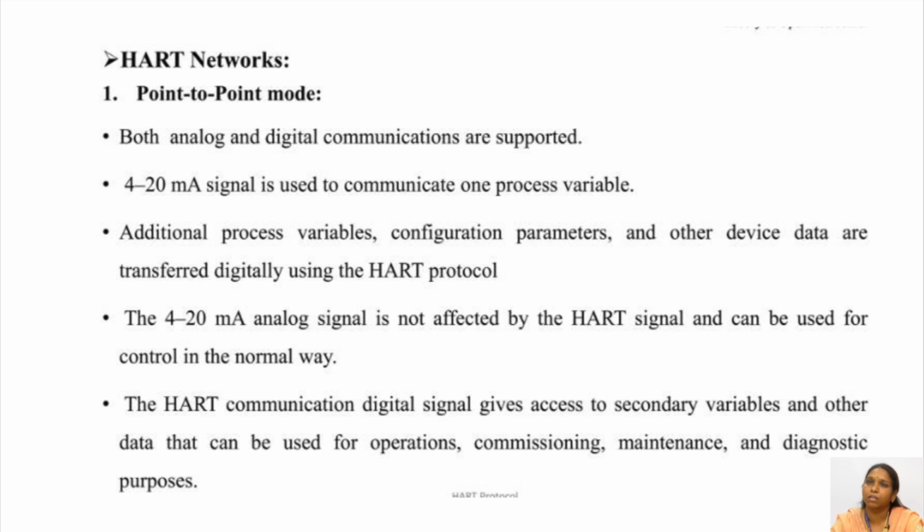HART network. First one, the point to point mode. Both analog and digital communications are supported. A 4 to 20 milliampere signal is used to communicate one process variable. Additional process variables, configuration parameters and other device data are transferred digitally using the HART protocol.